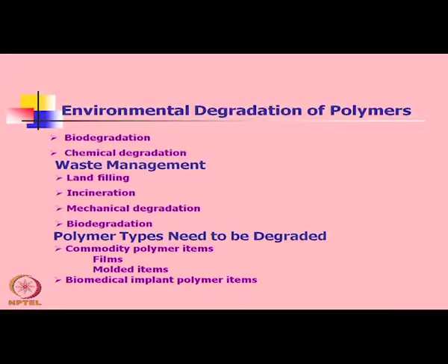Now, environmental degradation of polymers, we mean that when polymer products are exposed to the environment, in the environment there is humidity which varies from say 30 to 95% and sunlight, oxygen, ozone, thermal effects or other electromagnetic radiations that cause degradation, chemical degradation.